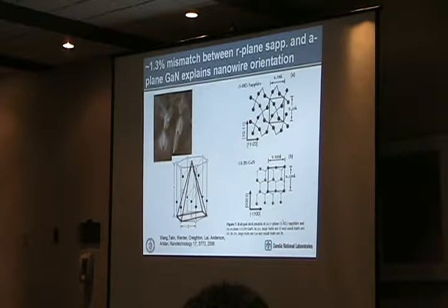Whereas right now, in CMOS, only at the first level is everything single crystal, but if you want to make a transistor on top of an oxide, it's already amorphous silicon or polycrystalline, and of course the mobility is greatly reduced. So we're looking at highly textured, oriented metallic films to see if we can still get highly oriented nanowire growth.